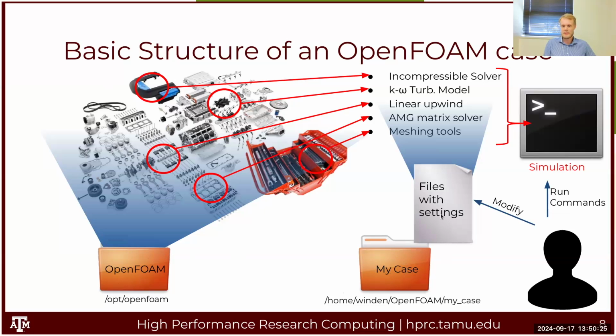This folder contains files, and these files contain settings. For example, there will be files that specify what the solver is, what the turbulence model is, what the convection scheme should be. And when you run OpenFOAM commands in your terminal, OpenFOAM will read these files, and it will pick from this OpenFOAM install location all of the components that it needs to assemble a working solver.